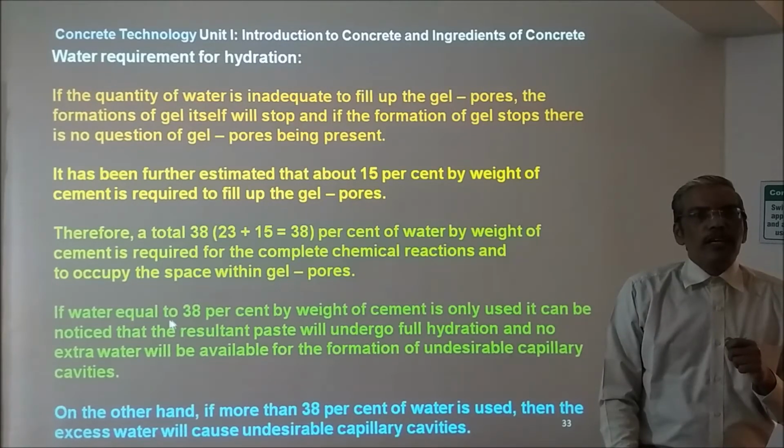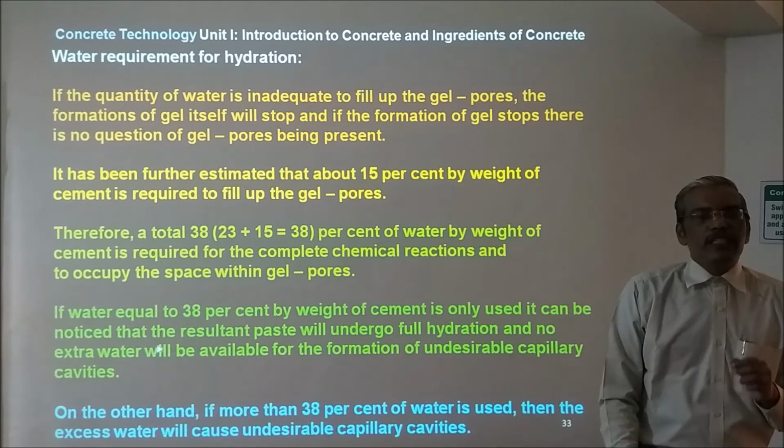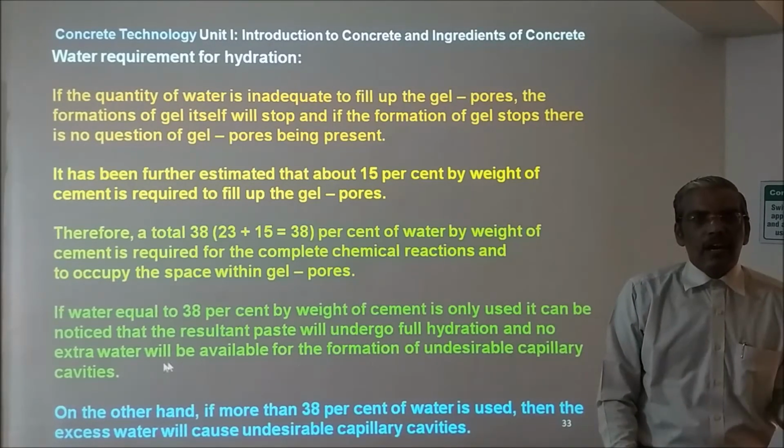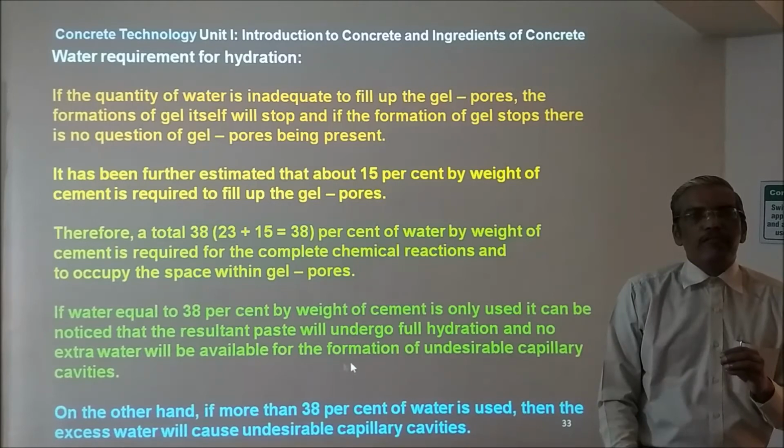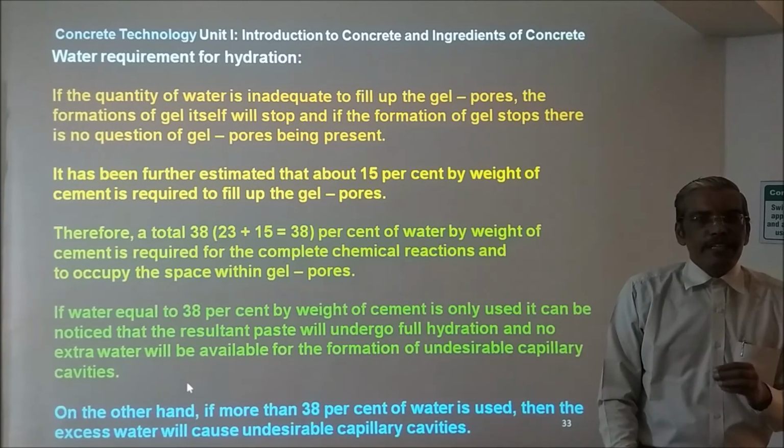If water equal to 38% by the weight of cement is only used, it can be noticed that the resultant paste will undergo full hydration and no extra water will be required for the formation of undesirable capillary cavities.